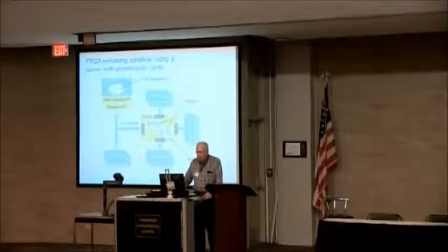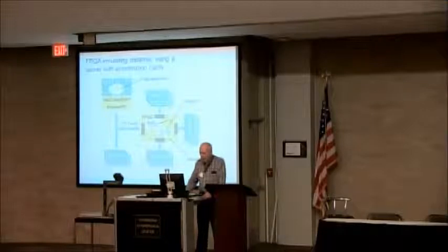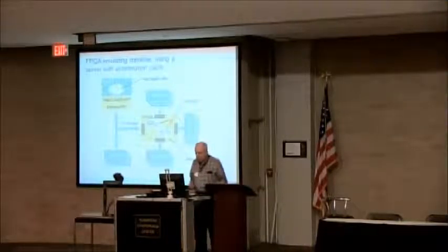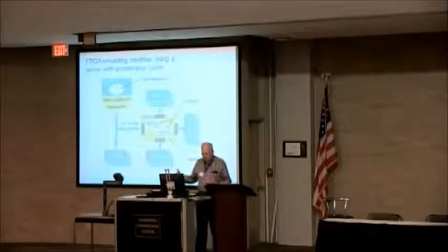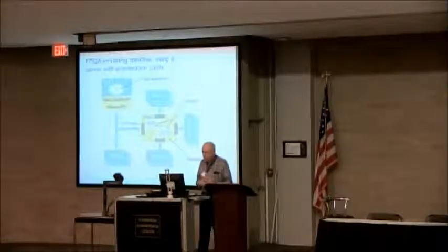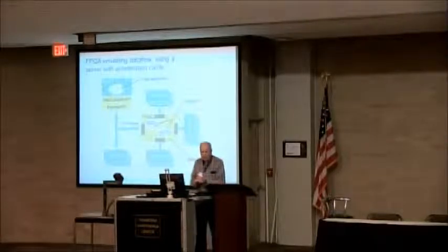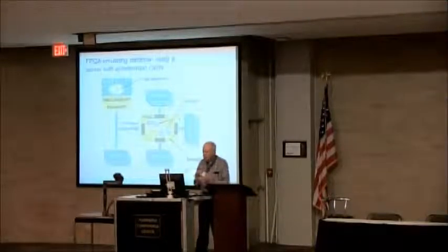We're going to use FPGA accelerators. The FPGA is going to emulate the data flow, and we're going to take a standard server, a high-end server, and we're going to use a PCI Express card with an FPGA on it, which represents the data flow of the compute-intensive portion of the application.